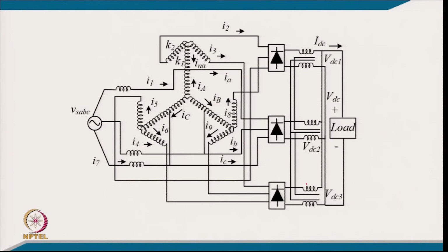So, this is typically the connection for 18 pulse configuration with plus minus 20 degree phase shift, with this fork kind of, typically umbrella kind of connections. One we are typically taking original, another we are giving the phase shift with respect to that, but we are making sure in design that all the voltages on the rectifier input are of the same magnitude. Why we have to use an interphase transformer: because we have to distribute the current in all the 3 bridges.